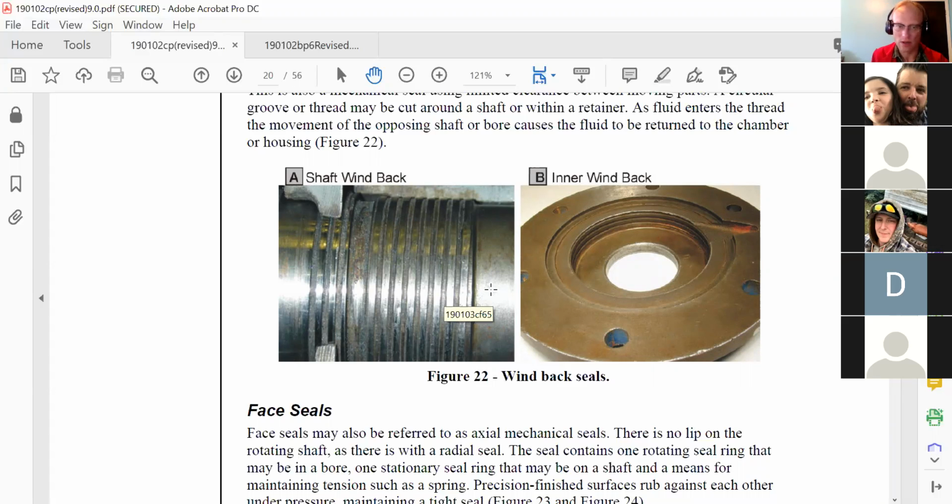Engines can run backwards, but they shouldn't. They should never run backwards. They're not supposed to, I guess, unless in very specific circumstances. But yeah, for this application, input shaft on a transmission, it only ever turns in one direction. That's how they can cut this in here mechanically in the steel and not worry about it, because they know it's only ever going to turn the one direction, this shaft.